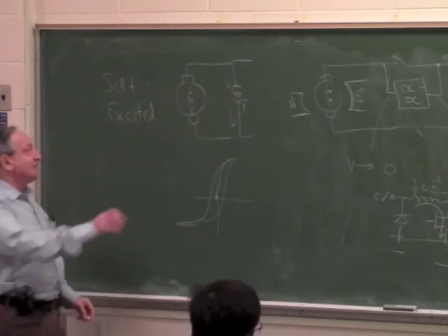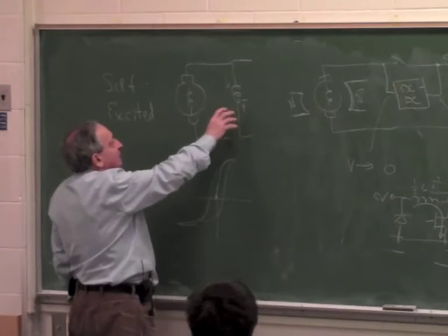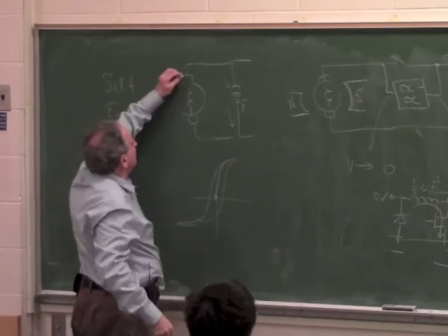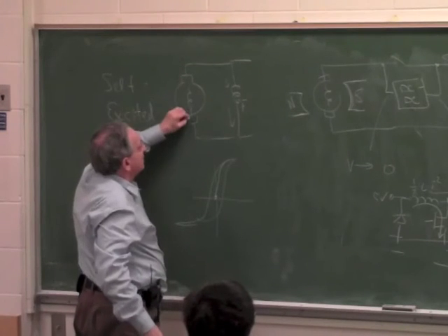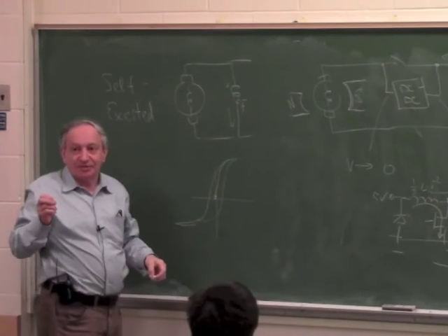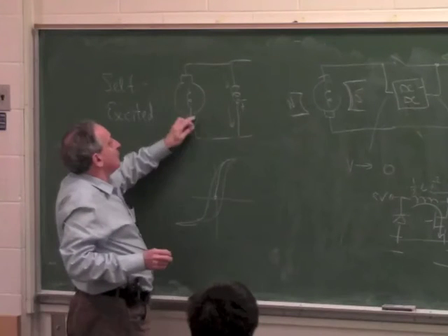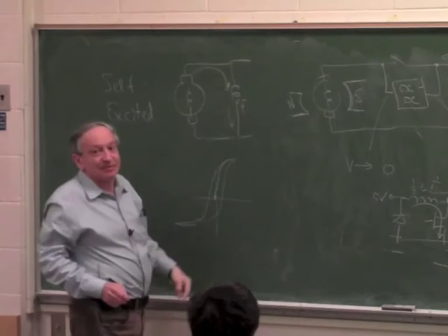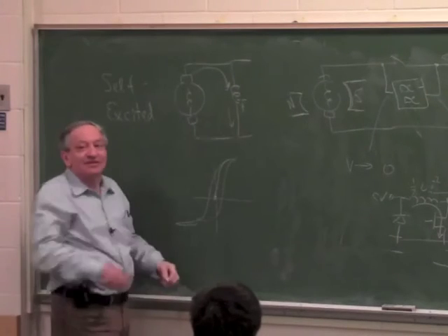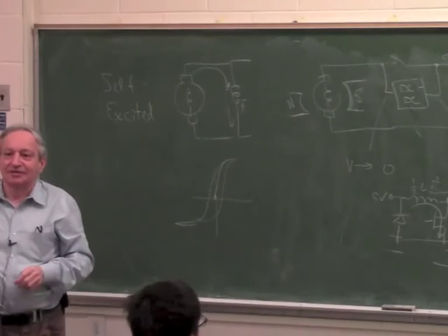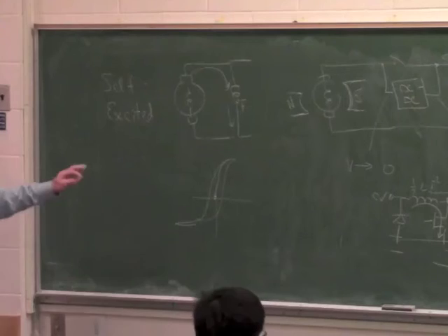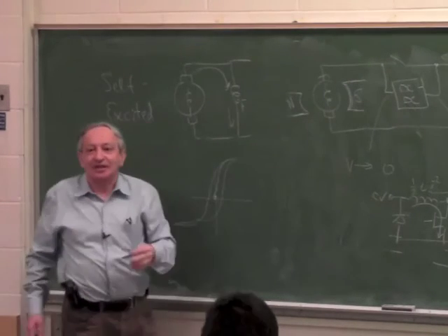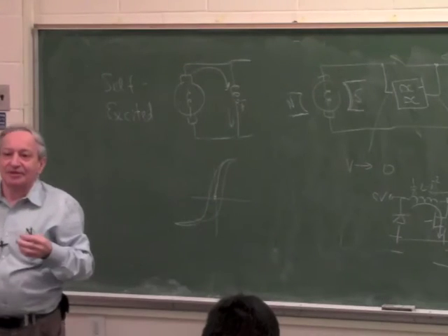So although this has no permanent magnet, it has a bit of magnetism, so when you start turning the motor, a bit of voltage is created here because of the residual magnetism. This little bit of voltage creates more current and more magnetism, which creates more current, so it's positive feedback. That's why even if a motor doesn't have a permanent magnet, it will still become a generator.